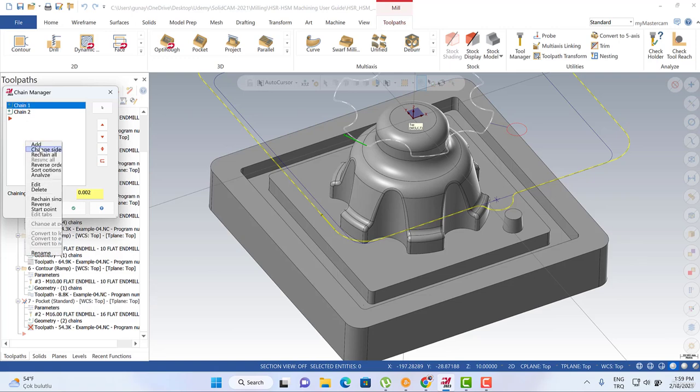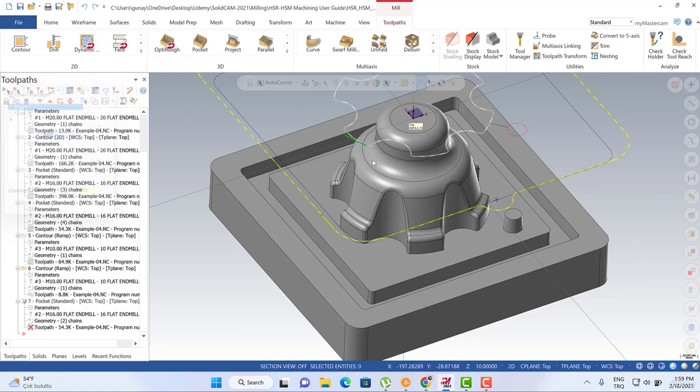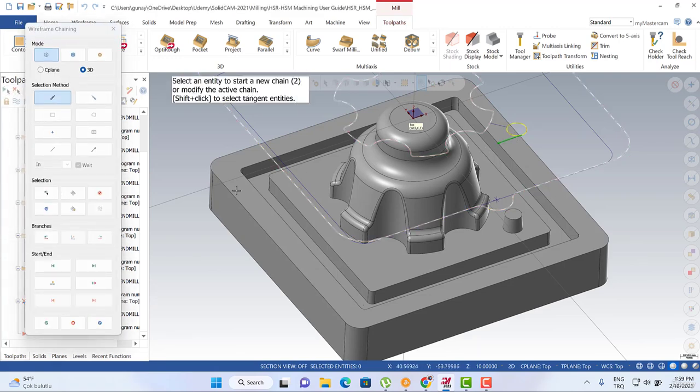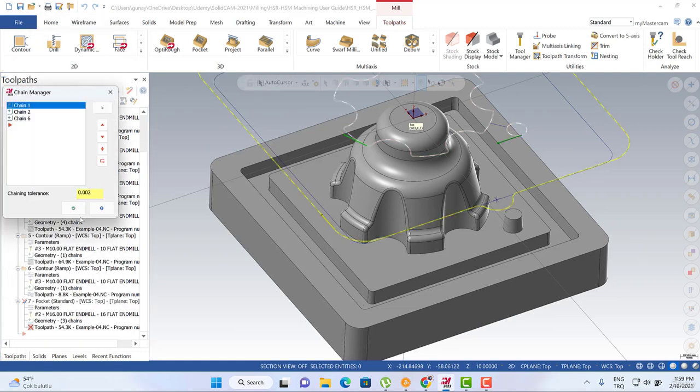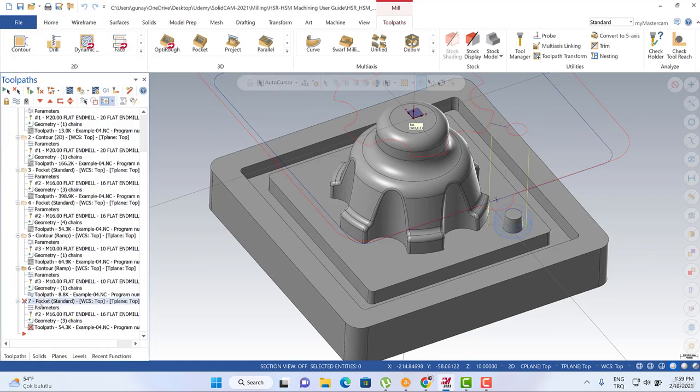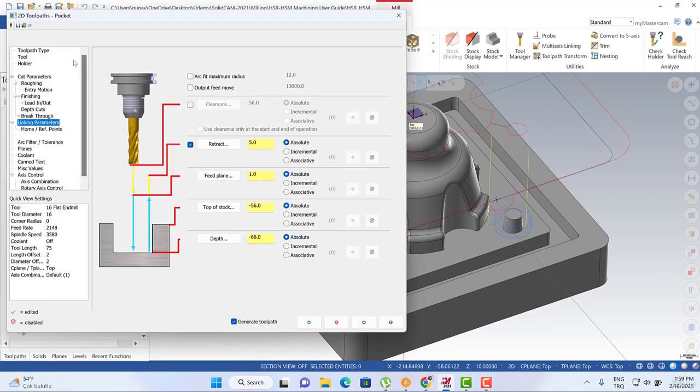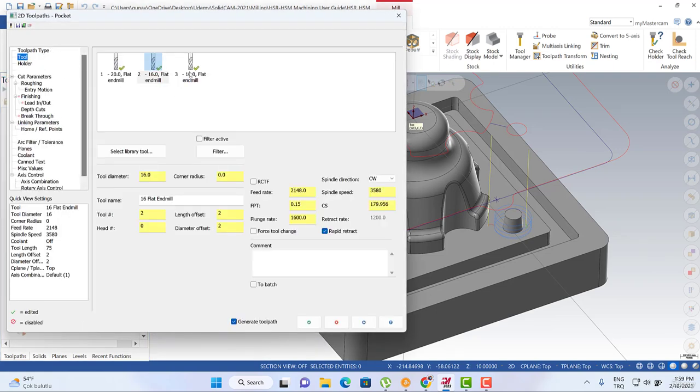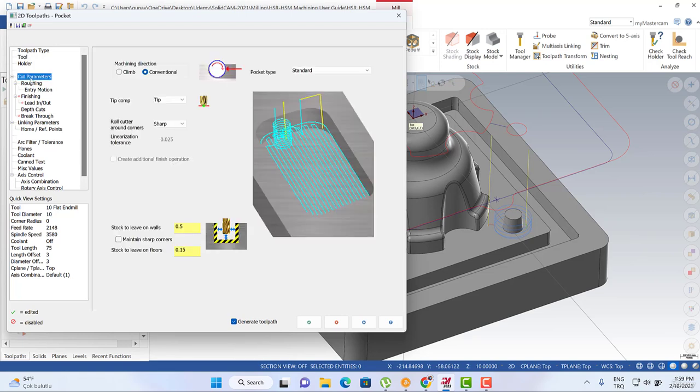Okay, I also need the circle, sorry, and can turn back here and add my circle here again. Okay, that's enough. After that, I can turn back to my parameters to change my tool. My tool can be 10 millimeter diameter. And then as cut parameters, we can make them 0 to 0. This is going to be my final process.